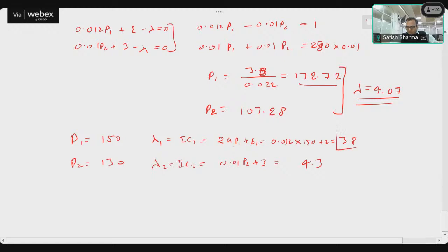Here, if I look at this particular one, I will not call it a system price, because the system price is when we are not enforcing any limits, and this lambda is not the true lambda, so I will not consider this one. It is with the maximum, enforcing the particular limit. If you look at this one, we are still not enforcing any limit, and it is whatever is left. So this will be our system price, our actual lambda. I will use this as lambda.